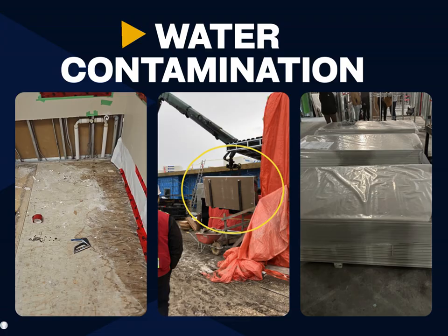When moisture and air are present, mold can grow on most organic materials across a wide range of temperatures. Because mold growth can begin developing within 48 hours, all water leaks or moisture events must be addressed promptly and IPC notified immediately. Depending on the extent of the contamination, a formal remediation and abatement plan may be required to safely address affected areas and prevent further spread.